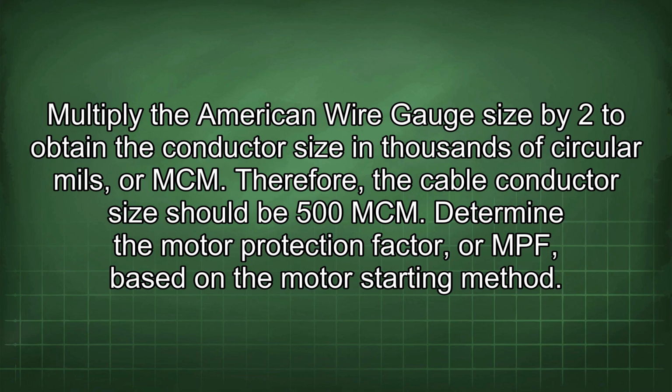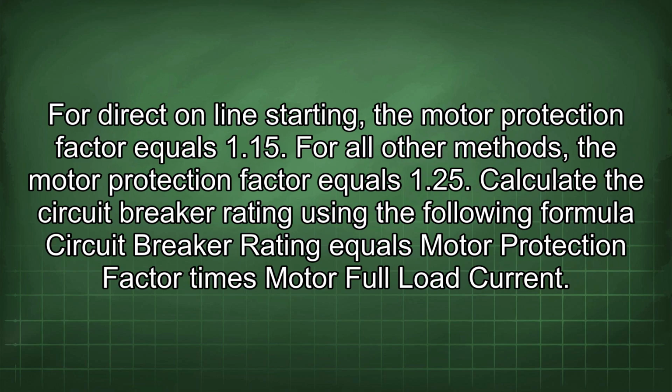Determine the motor protection factor, or MPF, based on the motor starting method. For direct online starting, the motor protection factor equals 1.15. For all other methods, the motor protection factor equals 1.25.